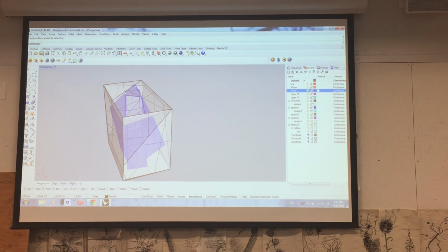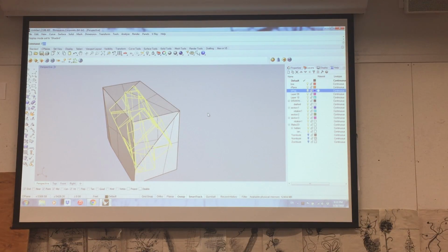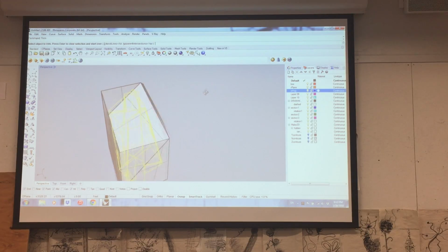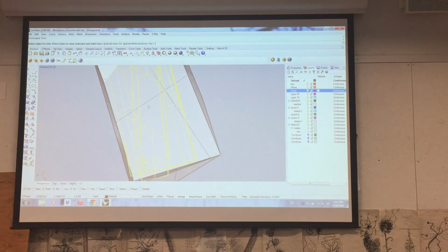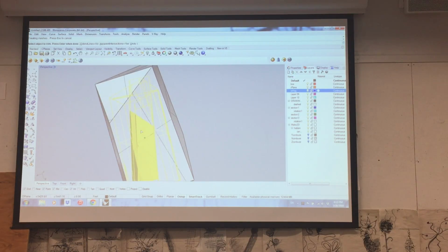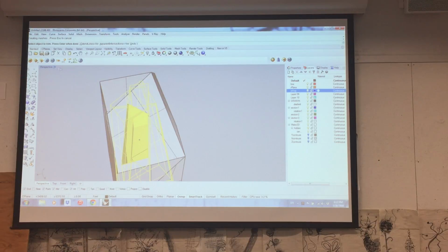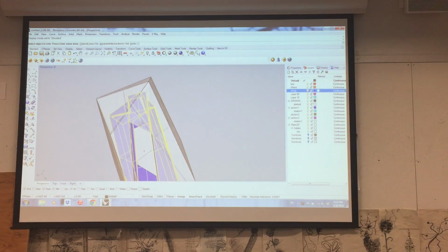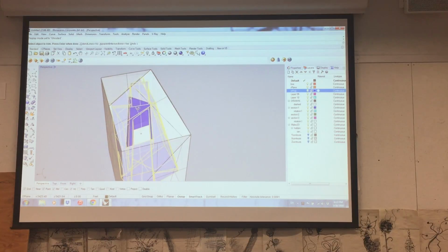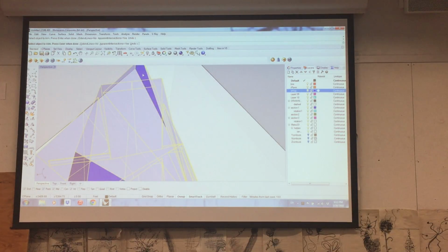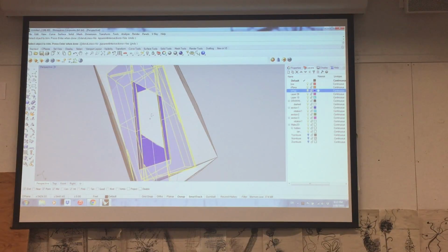I'm going to select the inside. And one thing that helps me doing things like this is I'll switch it to shaded view. And I will type trim. And I'm going to click in the region where I know that that trimmed area meets the top, so that when I click it, it only gets rid of that boundary there. I could go back to those just to make sure that it trimmed what I wanted it to trim. Right, that looks correct. And then I have this area over here. That looks good. And then I have bottom surface.